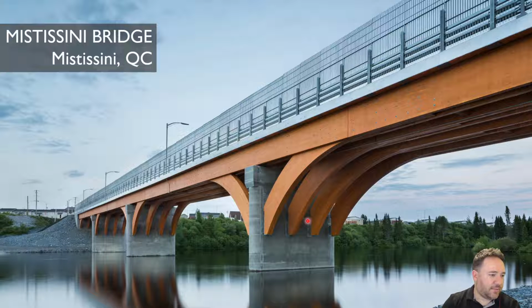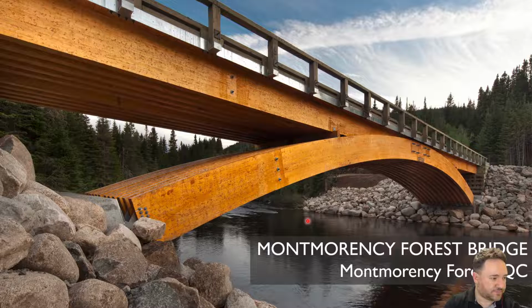And of course, the greatest concern here is going to be for drainage, so that since it's an outdoor structure with exposed wood, wherever the water gets to, it doesn't pool and stay there for a long time so that you get rot. So that's probably one of the main design considerations of the designers of this bridge. Here's another really nice example with a long curved arch picking up this roadway bridge in Quebec.